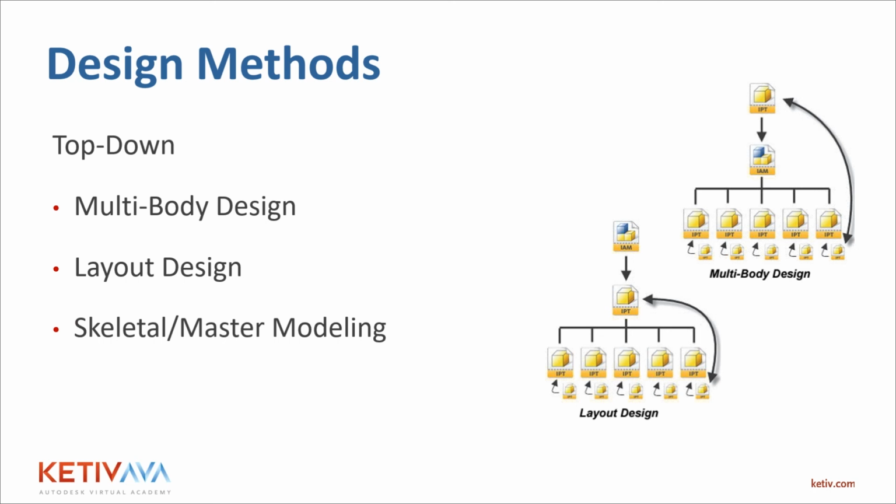They work much faster. The caveat there is you edit a part, change the size, it doesn't know to separate itself from another face. You have to manually go back and recreate those relationships, right? There's also a master model method that can sort of update those positions. These are all things we teach in one of our catalog classes on large assembly modeling. So certain things to consider. There are also some tutorials in the help files that I referenced earlier that point to some of these types of modeling methods.